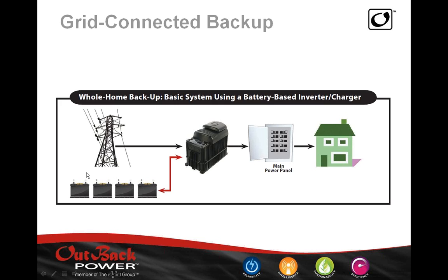One of the things that I've seen over time is that people will initially want to back up the entire home, but once you describe to them how much energy they'll be consuming, then that battery bank can go from a few batteries to a battery room. So very, very important to keep that in mind.